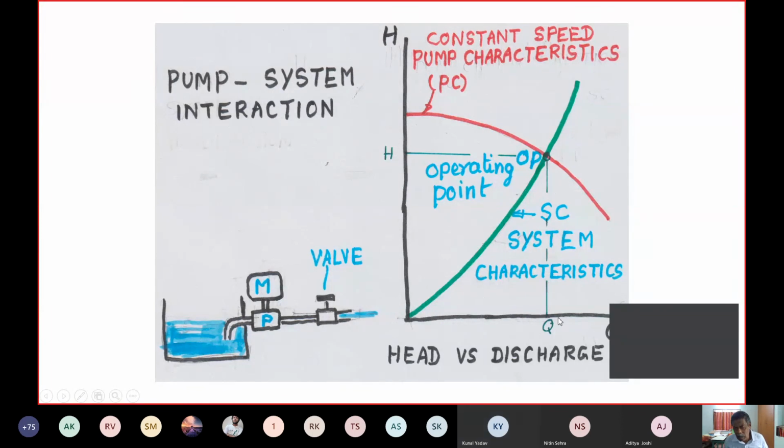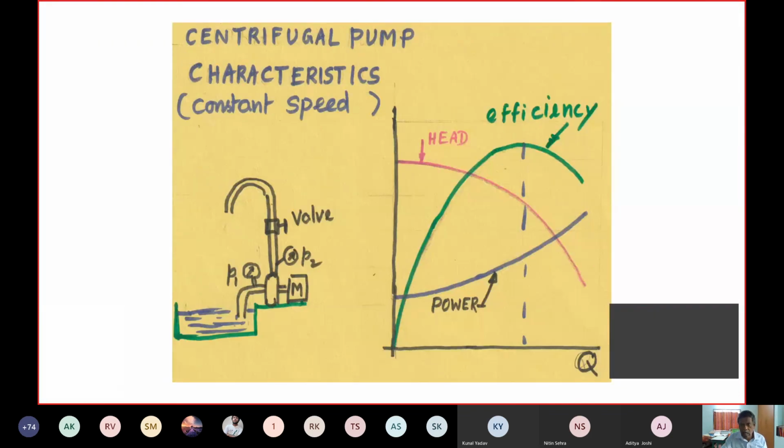Okay. So can we say that independent is actually how much we are opening the valve, and that is changing this head? Yeah, you can say it is in our control easily. So each valve position, I will get a discharge. That way also you can relate. So Q is the independent variable. Then correspondingly head and the full characteristics, you have all the three are there. Then you sit and calculate the efficiency. You will have some equation. Power, you will have the watt meter there for a few rounds.